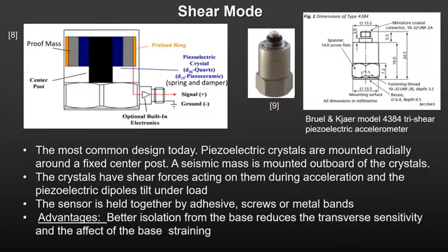In Shear Mode, the piezoelectric crystals are mounted radially around a fixed center post. A seismic mass is mounted outboard of the crystals. The crystals have shear forces acting on them during acceleration. The sensor is held together by adhesive, screws, or metal bands.